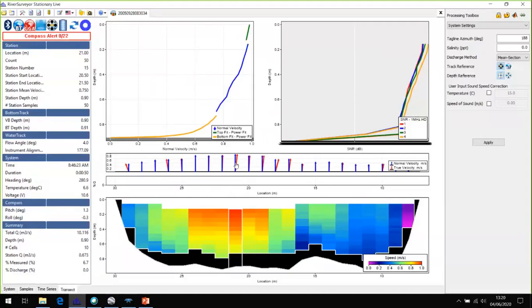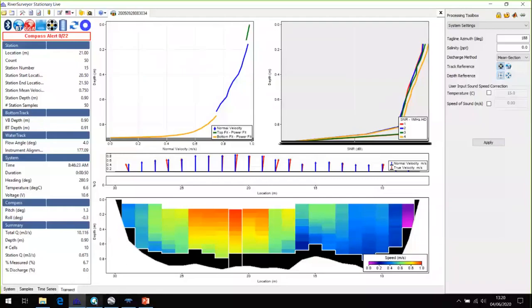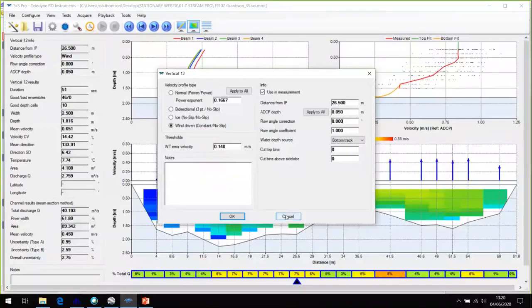Yeah. And that's why all this heading related stuff is important, because if you don't know your heading, you don't know how much of that red you need to remove, or how much you need to shorten the red to get to just the downstream component. Heading is really important, and is a key distinction, I think, between this mode and a bottom track reference mode, where it's all to do with reference boat speed and water speed, and the calculation comes from a different formula.